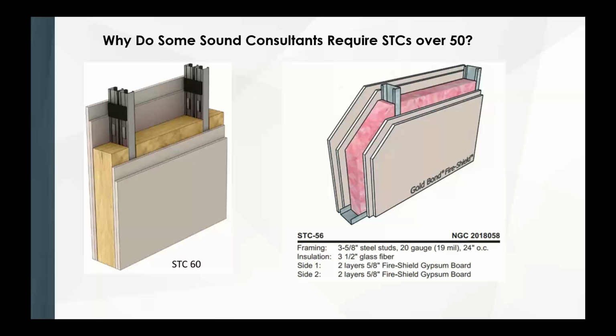A lot of times they'll do something like this. You'll see different products out there that can do this. This one has a gasket connecting these two studs together that again is going to reduce the vibration going through the wall. Or over here, they're just adding another layer. So maybe the wall requirement is just for a 1 hour rating, but you can see that they added double layer on both sides. That's for the STC ratings, not necessarily for the fire ratings.